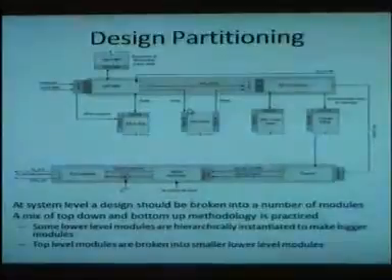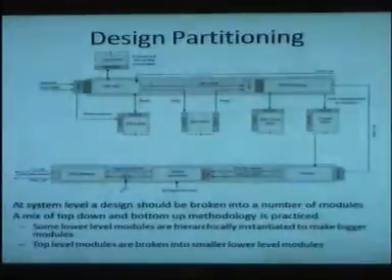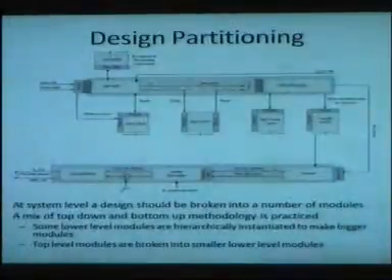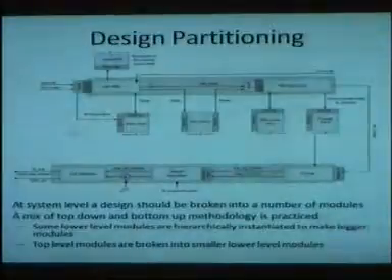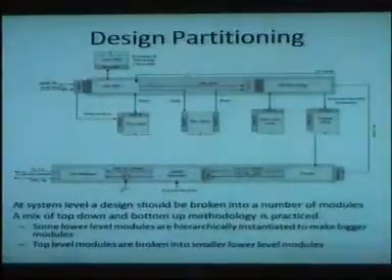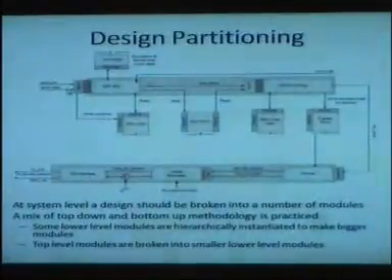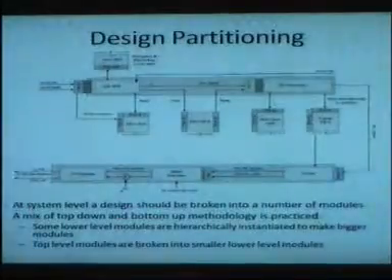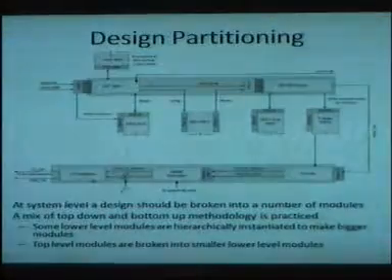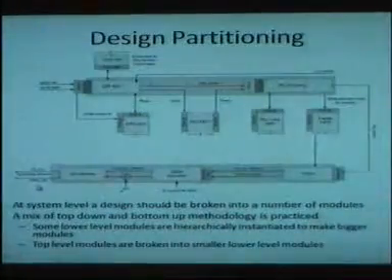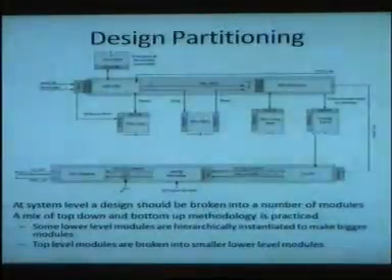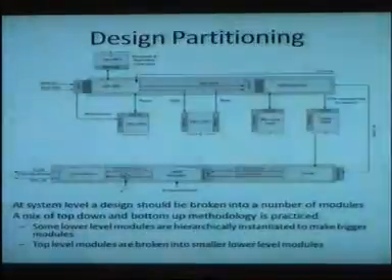That's how Verilog is also structured, that you have a top level design. A top level design is a big box which has all of these, and the input signal to that box is just a serial clock and a serial data. So every positive clock edge you get a bit, and you have to collect all these bits to make a word, because it's a serial interface. Then at the D2A interface, you have 12 bits of data at a clock. At a clock you throw 12 bits, 12 bits, 12 bits, all the time. So at the top level, this is how the module is.